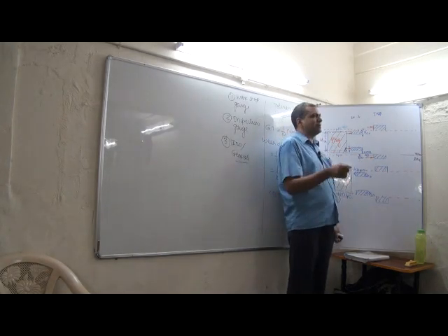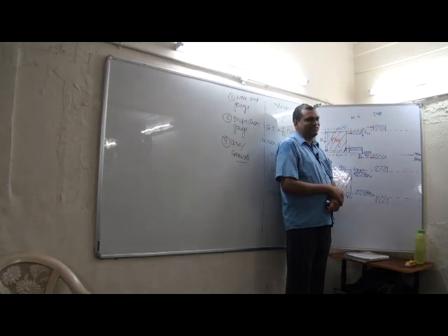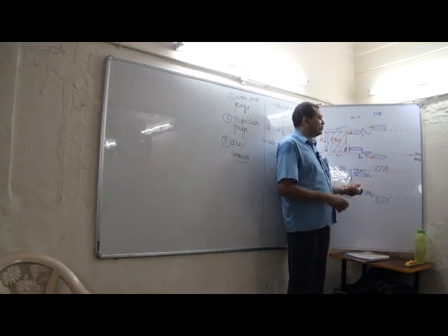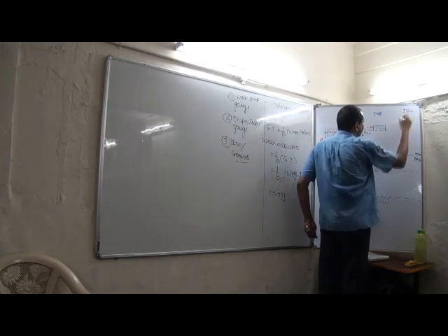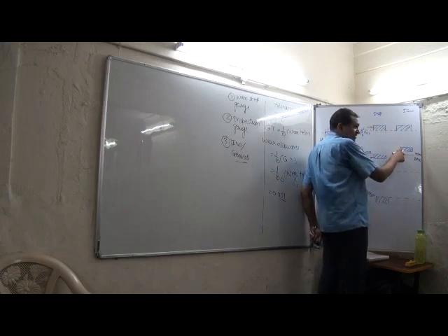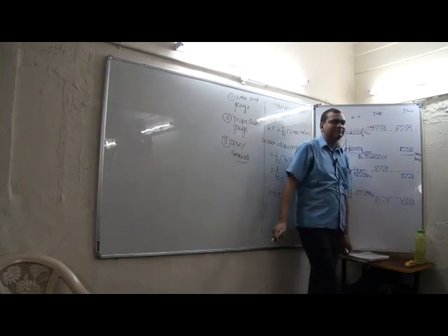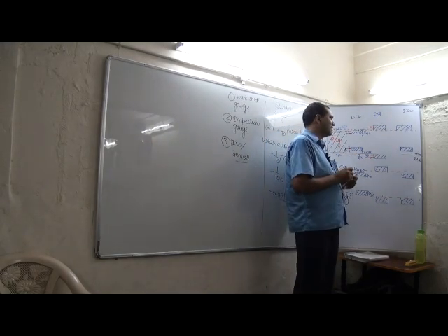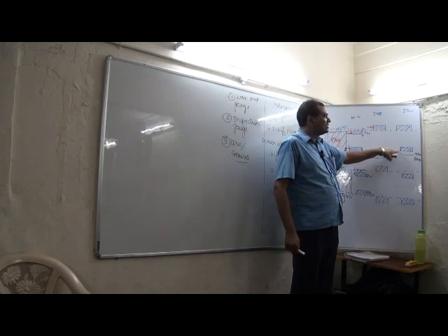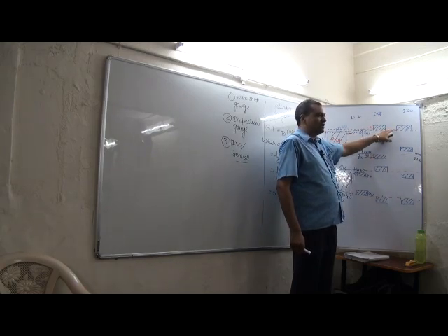According to ISO or general purpose gauge, you take go from the workshop and no go from the inspection. So 50% you, 50% you. Have an agreement. So ISO gauge will be, this is your go. We have to provide allowance on the go gauge because we are taking it from the workshop. This is go. This is no go. So in ISO gauge, on the go side, we are rejecting some good parts. On the no go side, we are accepting some bad parts.